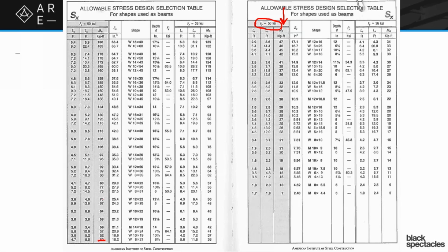Now, this is kind of a little counterintuitive for a lot of the architects out there, because if you start to imagine say a 3-inch difference or something like that, and let's say it's a multi-story building, and so I'm now adding 3 inches at every floor, I could very easily have actually a very inefficient choice that way.